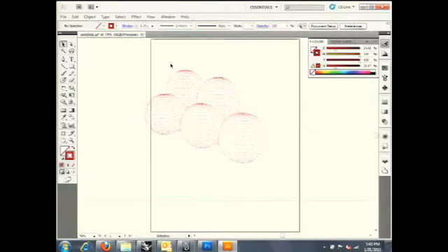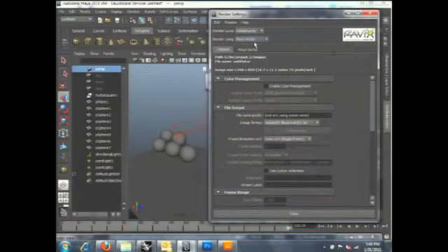Okay. Any questions about Maya rendering? So let's repeat one more time. We have Maya software, vector, and mental ray. Maya hardware rendering is only for particles. You don't have to know this. In the future, if you do want to render some special effects like smoke, fire, or particles like snow, you can use Maya hardware. It's pretty good at handling these particles. All right, so that's pretty much about rendering.